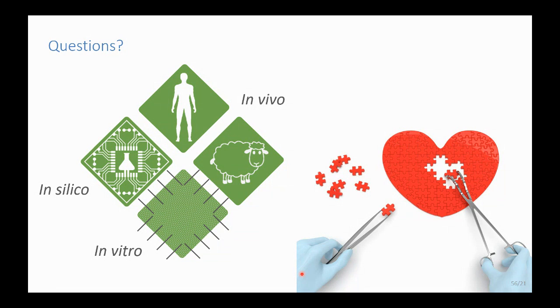It was a really nice presentation, really enjoyed that. So I had two questions. The first one was, in your fiber reinforced hyperelastic model, I think that there's no time dependency, so you basically have a given strain rate, which is the one that you've used probably from your bioreactor testing, so your results might be very dependent on the strain rate.